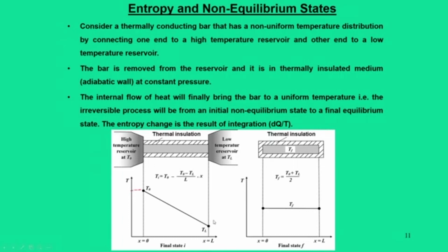So these are the conditions for the amount of work done for the refrigerator. This is the situation. The minimum work is T1 into (S1 minus S2) minus Q. This is the minimum work required for the refrigerator, from the entropy principle. I conclude this lecture. Thank you for your attention.